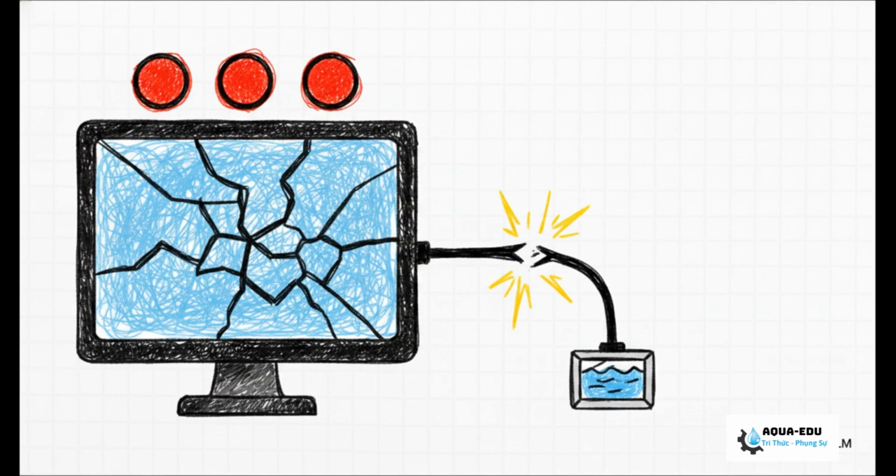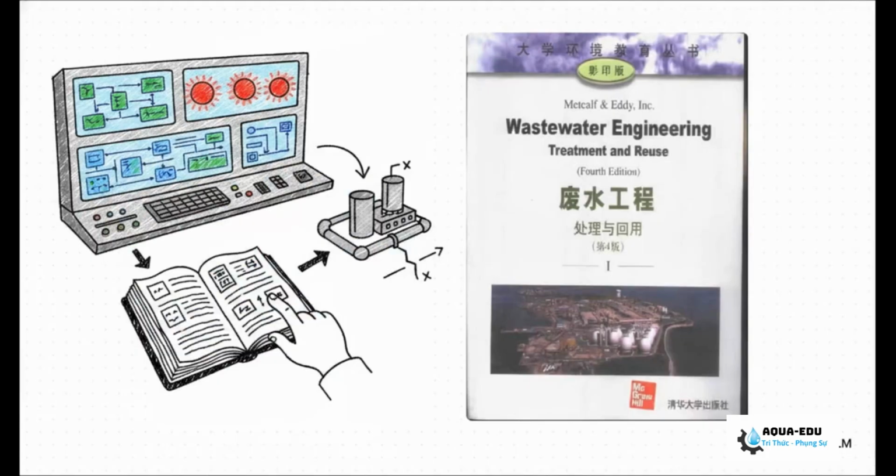Furthermore, if you see a continuous red bad quality tag popping up on the panel or solid red indicators for sensor faults and comms errors, you are looking at a massive communication breakdown between your sensors and the PLC. Listen, brothers, when you're sitting at these control room interfaces, you've got to constantly be scanning your screens for these solid red fault lights. They are your earliest warning sign of a system disconnect.